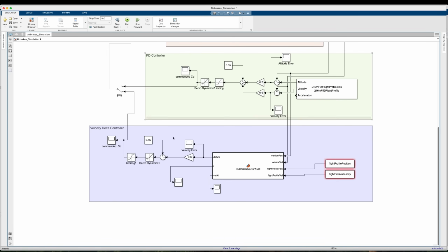These first two guidance and control systems are something called reference trajectory controllers. So we're controlling based off of a reference trajectory. My assumption for my rocket is that my starting drag coefficient with my Airbrakes closed is 0.4. That comes from OpenRocket, and it's probably pretty accurate. My assumption is that my maximum drag coefficient is 0.7. I made that number up, and in our first flight test, we'll see how close I am to reality. That is a vibes-based engineering approach, which doesn't always work, but that's okay.